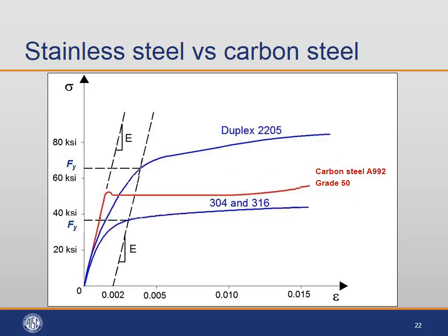Right. So the question was, why is the strength there closer to 40 KSI? Now the reason is that these are actual measured stress strain curves of bits of stainless steel that we stretched, and the codes give the minimum specified data, which is down to some 95% confidence level.